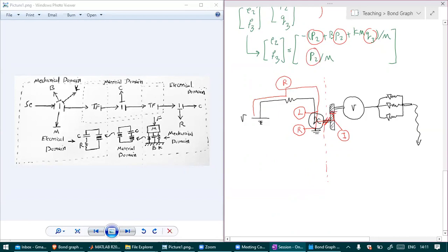Again, here we have a transformer because we know the velocity of one gear is different from the velocity of the other one. And also we have inertia there. Then the flow goes to the hydraulic domain. So we have a transformer or a gyroscope there. We have to decide it. Let's assume there is no behavior other than just this transformer behavior for the pump.